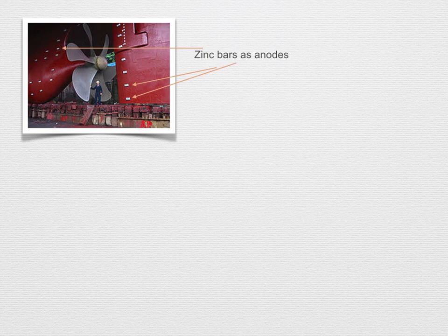Anodic oxidation seeks to remove electrons from a metal to produce the cation of that metal. Normally this would be the iron that is being oxidized. However, the zinc has a more negative reduction potential, and so it gives its electrons back to the iron to keep it in the metallic state, while zinc corrodes preferentially. The iron becomes a cathode in a cell with the zinc and is protected cathodically. The iron is reduced by the zinc as quickly as it is oxidized by the dissolved oxygen in the seawater in which the ship is sailing.